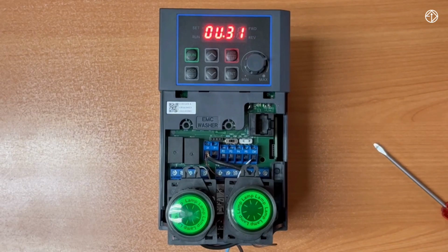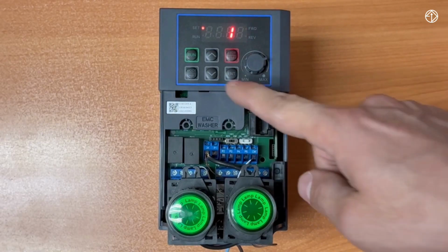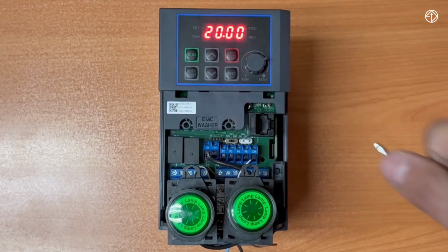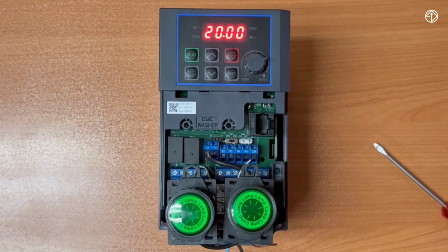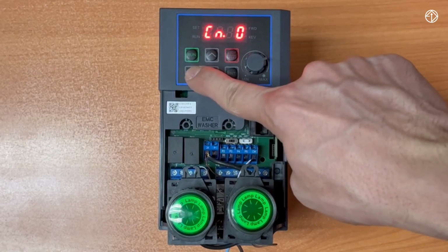For relay 2, we want it to activate as soon as the frequency reaches our command frequency. For example, if we set the frequency to 40 Hz, when it reaches 40 Hz, or in other words, when it reaches the steady state, relay 2 should activate. We said that for this, parameter OU33, which is related to relay 2, should be set to the value 16. So relay 1 activates as soon as it runs, and relay 2 activates as soon as the inverter reaches the command frequency, for example, the 40 Hz that we define. Now I'm going to set a 40 Hz command here for the inverter.